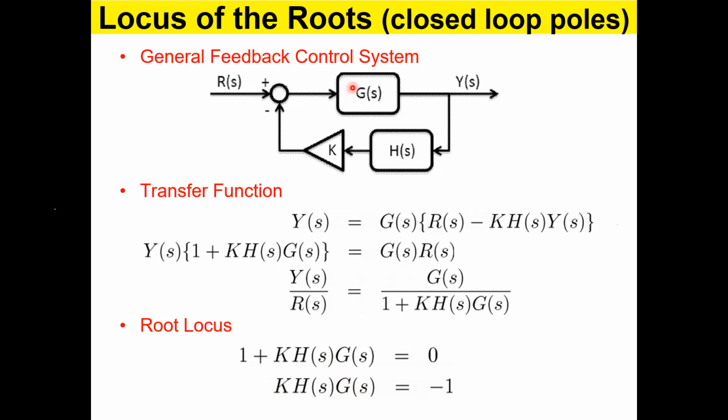Now this is a really interesting case. We analyze the closed loop transfer function but using the open loop transfer function. Understand? This is the open loop transfer function. So we analyze the behavior, the characteristics of the closed loop transfer function using the open loop transfer function, because the open loop transfer function is very easy to handle. Feedback, when you get the loop closed, it becomes a bit complicated. In the physical world, we do the connection and everything. But to analyze the plant, we can do almost everything using the open loop transfer function. So that is the beauty here. Okay, right.